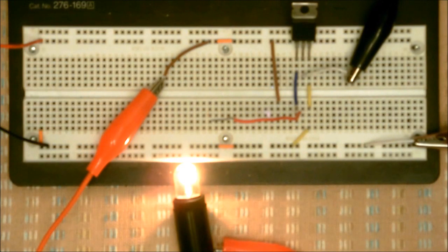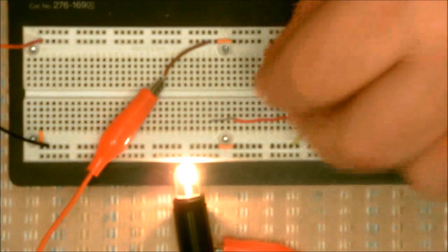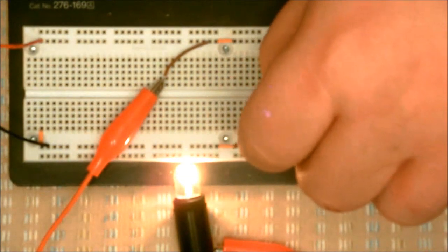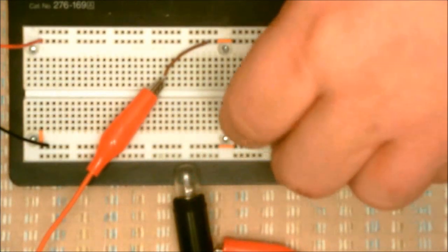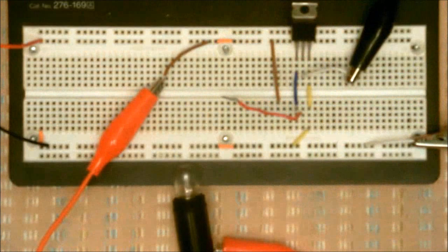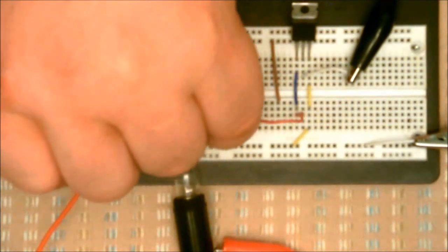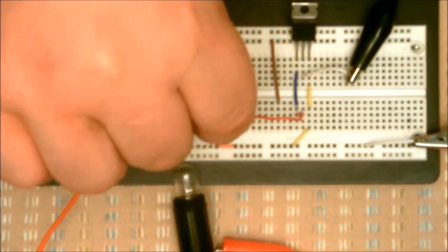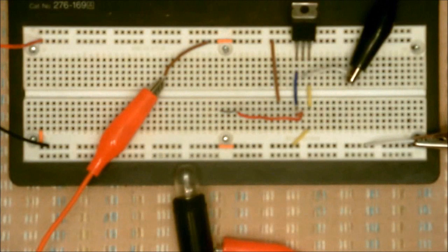Well, all you have to do on this transistor is ground out the gate like that. And now the transistor is turned off. Now, because I got my wrist strap still grounded, I can go back and touch it and rub the carpet and nothing will happen. This is the best way to protect these.